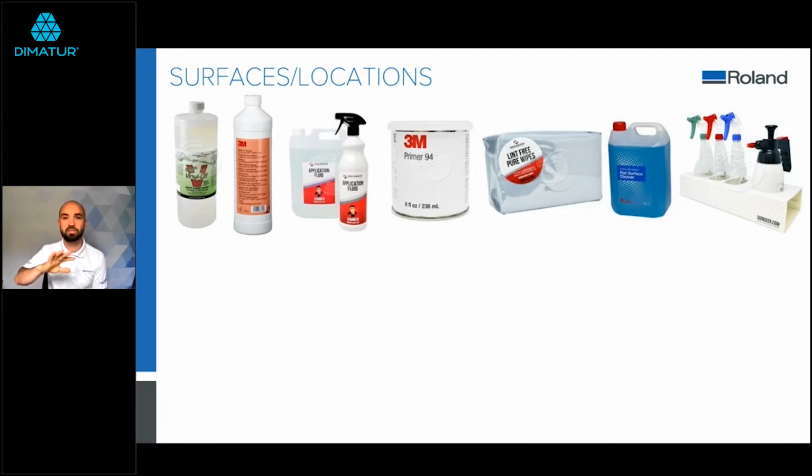If they have lots of imperfections in the wall, you may want to give them a light sand as well. Again, if you're going to light sand the wall, then you're going to need to get the sanding dust off afterwards with a damp cloth and then wait for that to dry before applying your graphics. These may seem like quite advanced steps to go through, but it is going to make your graphic work and last better. So it is worth taking the time to make sure that your surface is as clean as possible.